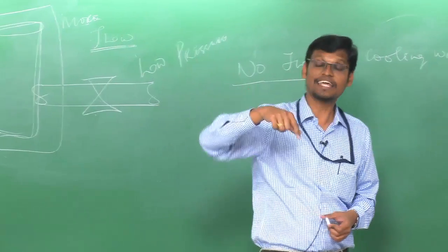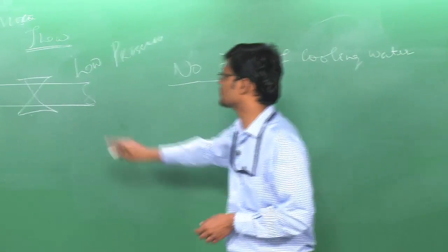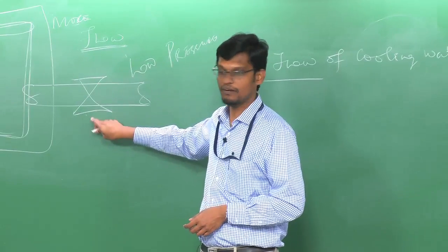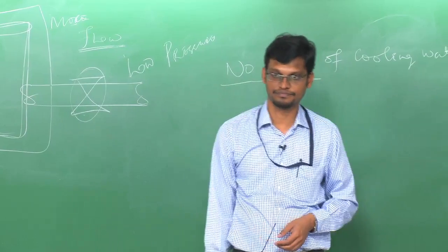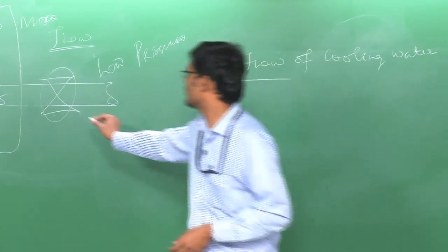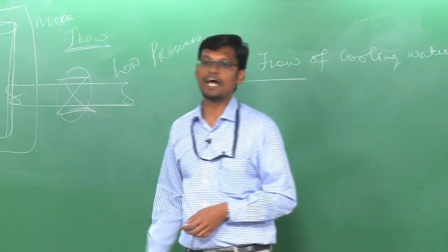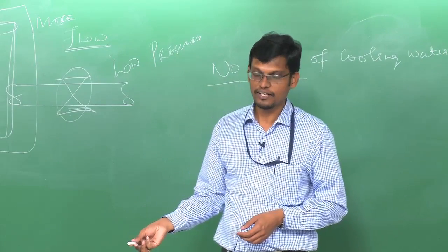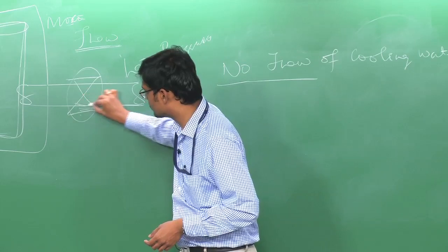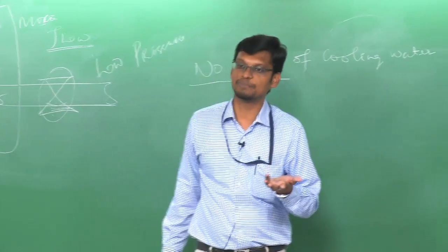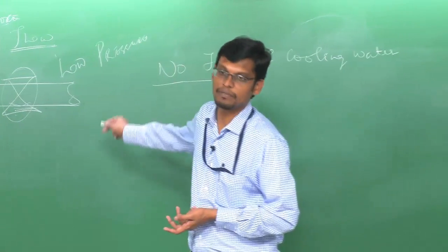Now where the input comes is, for example, you talked about the valve. Can this valve malfunction? You have a valve passing. If you have a valve passing history already, then you look at the valve seat. Do you want to go in for a specific material which is compatible with the chemical you are using?